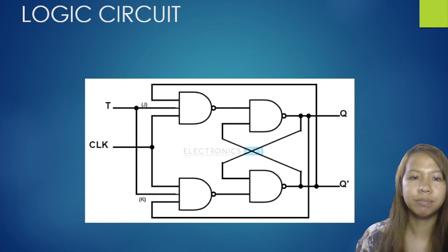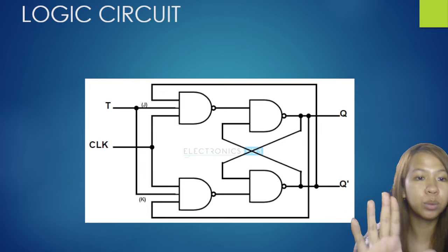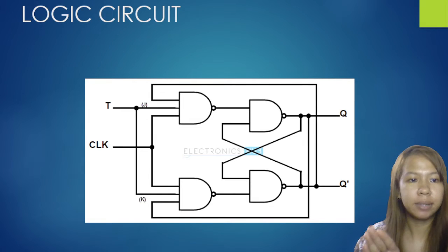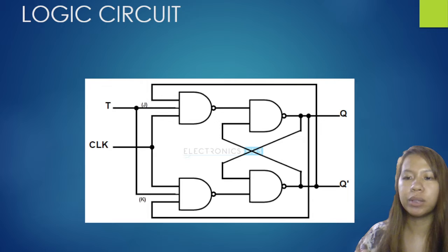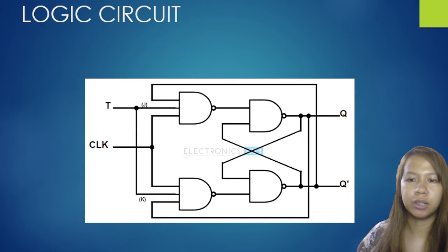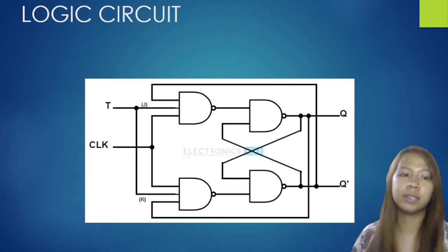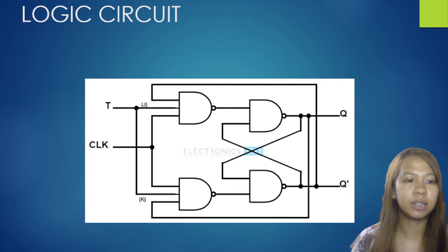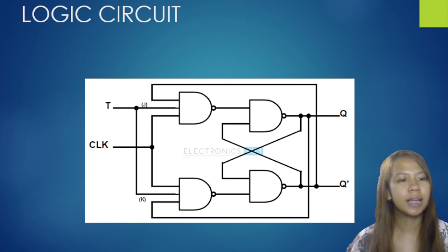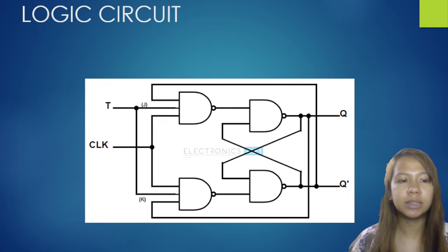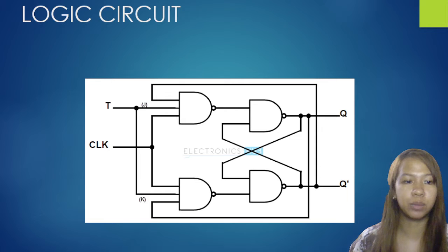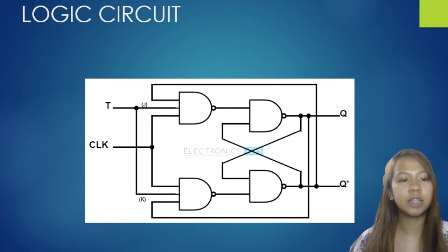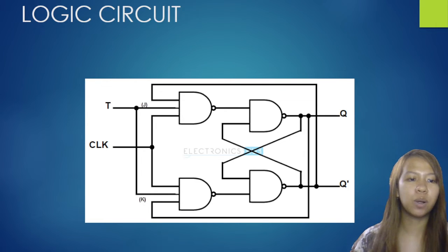The pulse transition detector (PTD) converts a rising or falling edge into a short pulse. This pulse becomes an enable signal such that the latch is enabled only for a short period of time following the transition. The latch and PTD arrangement is what we call a flip-flop.